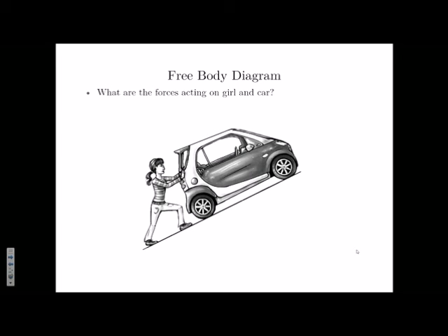In some cases, it will be very clear when you should take into account the friction forces. For example, if you have, let's say, a two-wheel drive car, and it's a front-wheel drive car, then the torque from the engine is being applied on the front wheels only, which means that there will be friction forces on the wheel from the ground on the front two wheels. But your rear wheels are not driven by the engine, so you neglect the friction forces from the ground on them, because there is no traction available to the rear wheels, right?